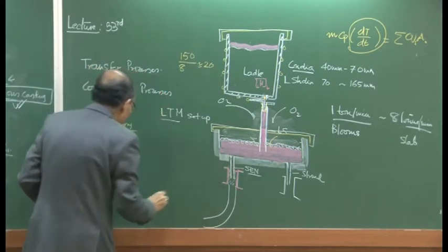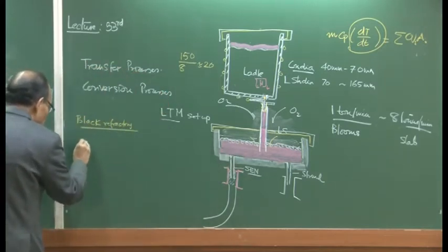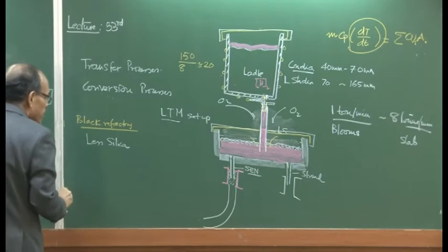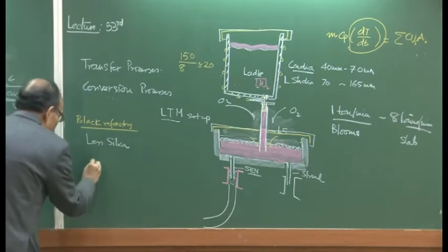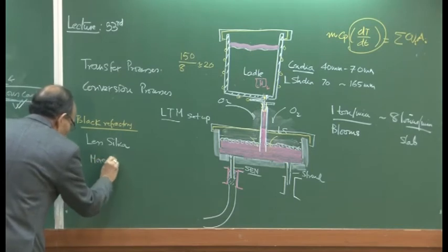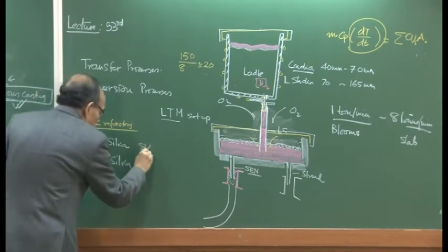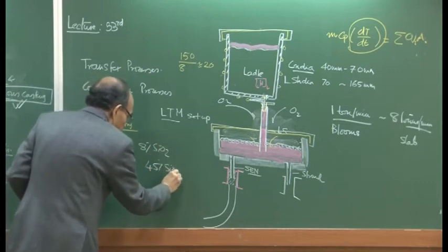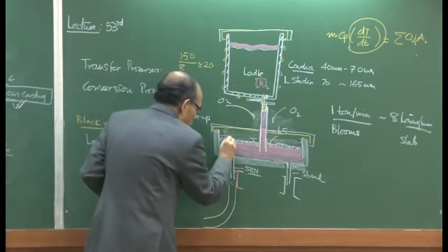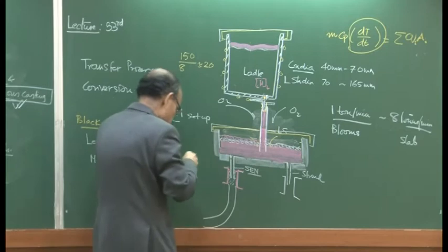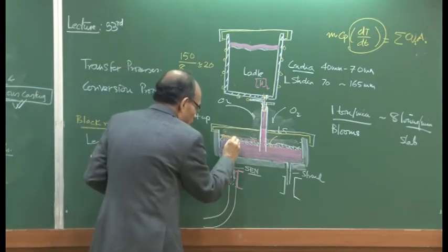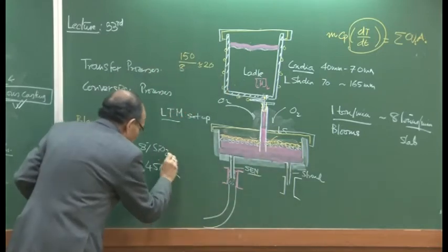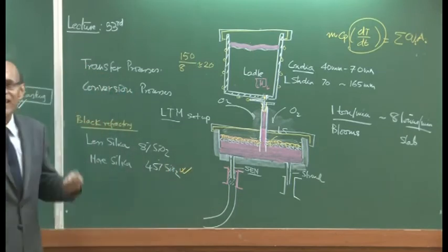The powder which is in contact with the steel contains less silica, about 8% silica or so, and that which is above this powder has more silica, about 45–50% silica. So we have two different kinds of powders, and the upper one, the yellow one, is basically called the tundish covering compound. This is the insulator basically.